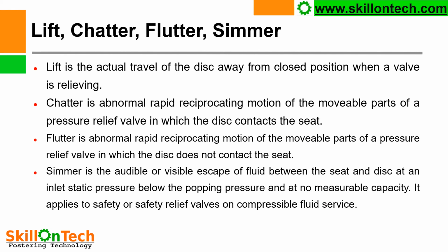And some other terms also: lift, chatter, flutter, simmer. Lift is the actual travel of the disc away from closed position when a valve is relieving. Chatter is an abnormal, rapid, reciprocating motion of the movable parts of a pressure relief valve in which the disc contacts the seat. So you will hear a chattering sound. Flutter is an abnormal, rapid, reciprocating motion of the movable parts of a pressure relief valve in which the disc does not contact the seat.